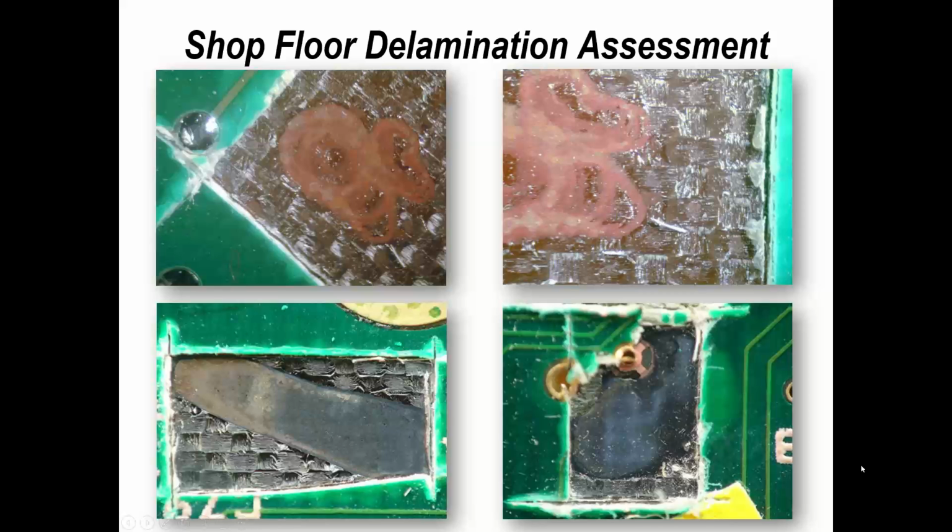Now back to, again, the boards and delamination. You know, I mentioned earlier about the shop floor test. I just included these 4 photographs, from 2 different boards. And what you're looking at here, again, is poor bonding. So originally, where I've cut it out with a knife was a blister. So it delaminated. You could see it as delaminated. So basically, all I've done is go round the blister and cut it out and remove that section of the board.